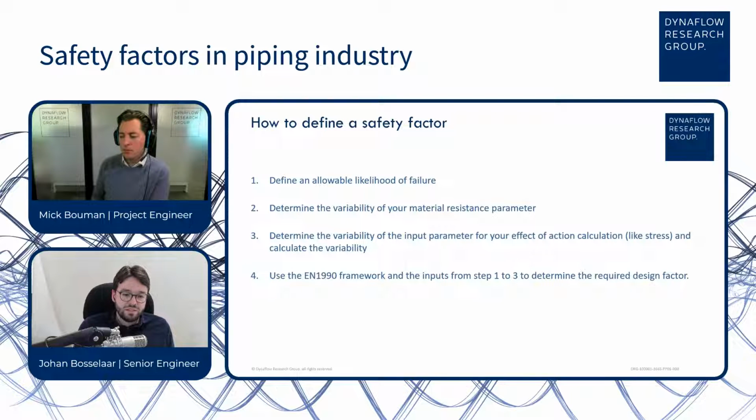Yeah, I can imagine that just stealing it from a different standard isn't sufficient for fiberglass material, right? Because it is quite a different material than, for instance, steel. Yeah, true. So it is also very important always to use material properties, calculation methods and safety factors within the context of a single code. You shouldn't go shopping between standards, using material properties from one and a calculation method from another, because it is a single framework that works as a whole.